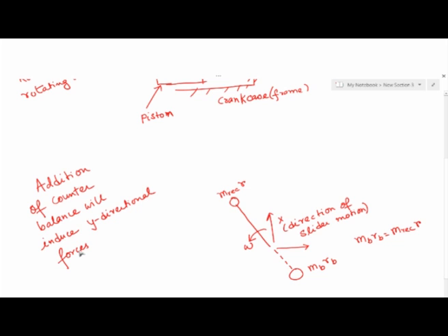In the original system, without the addition of your counter masses, there were no y directional shaking forces, there were only x directional shaking forces. You realize that those x directional shaking forces are equivalent to the x component of the rotating unbalances with magnitude MREC times R. So you thought that by putting a counter mass you should be able to resolve the situation, but though you have killed the problem in the x direction, you have made a new problem by putting a counter mass in this fashion.